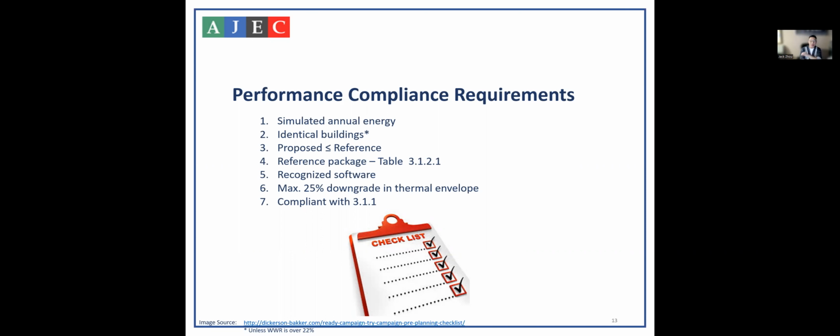Now, in the next version of the building code, they're asking you to not only include window glazing, they're going to ask you to include door area as well. So they don't call it window to wall ratio anymore. They call it fenestration to wall ratio. And that includes doors and sliding doors and also actual door openings, opaque doors. So that's going to be a new change you guys have to learn.